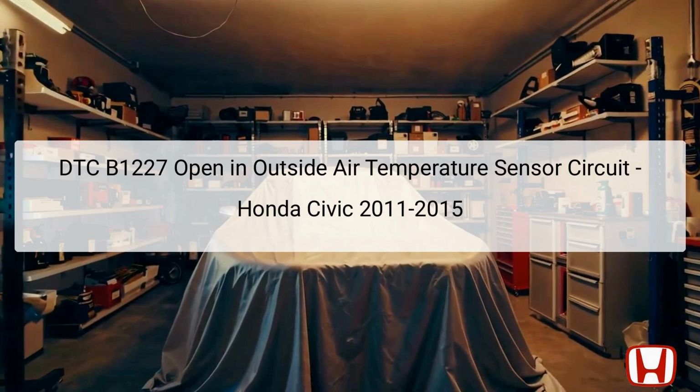The DTC B1227 error code, also known as indicator 05, indicates an open circuit in the outside air temperature (OAT) sensor circuit of the Honda Civic models from 2011 to 2015. This sensor is vital as it provides information related to the outside air temperature, which is essential for the climate control system to function effectively.